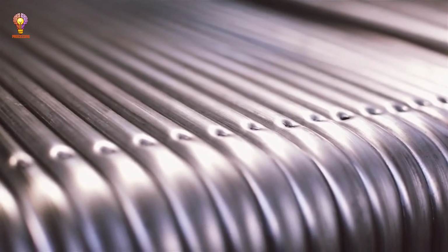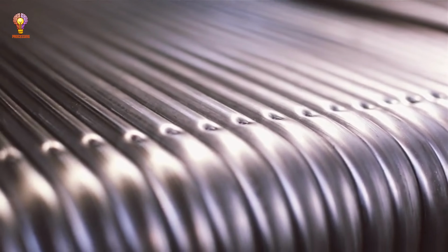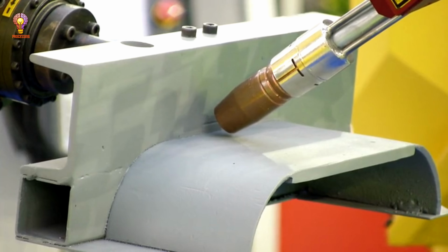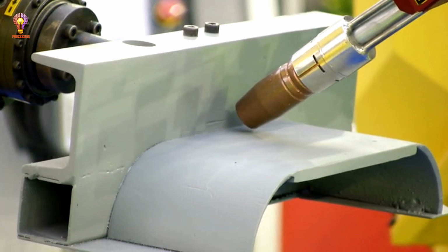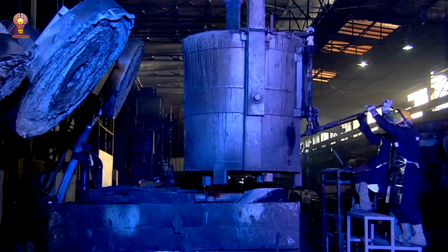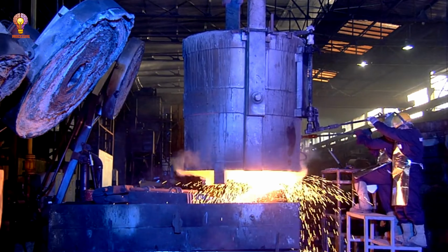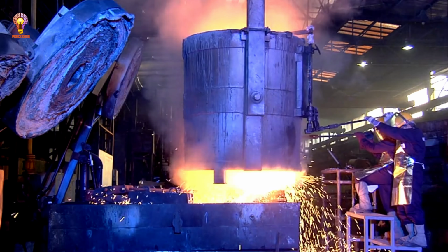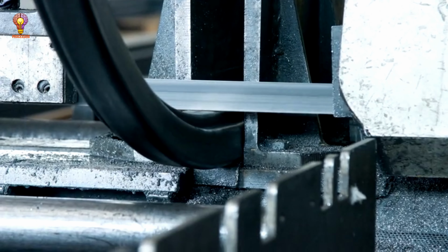Titanium steels. Titanium steels are designed to be highly resistant to corrosion and high temperatures. They are used in highly specialized applications such as aerospace, military, and chemical industries. The challenge in manufacturing these steels is maintaining their high strength, while preventing titanium from negatively reacting with other alloying elements. Tool steels and high-speed steels.